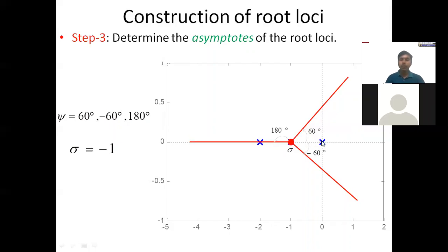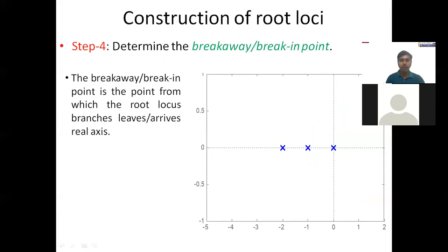And therefore, it will start from here, and somewhere it should divert its path, follow this direction and reach infinity. Therefore, in the middle of this, at one point, this diversion takes place. That point is nothing but the breakaway point. We'll see how to calculate the breakaway point.